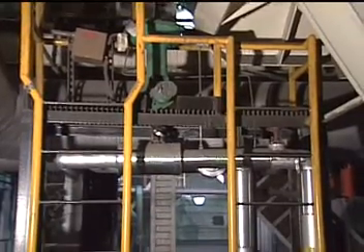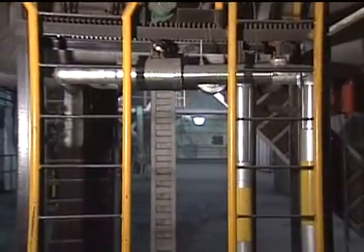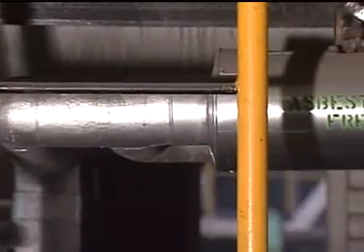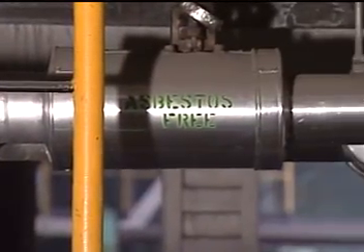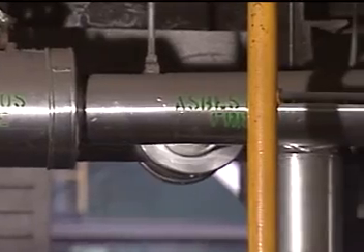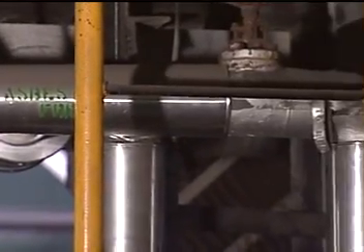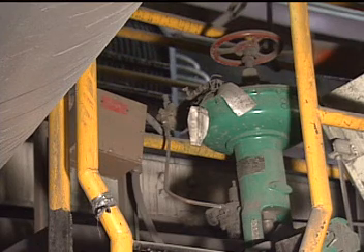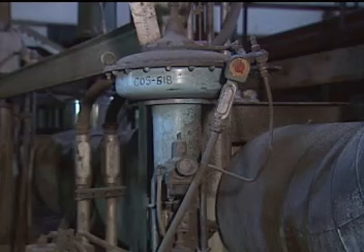The components of the temperature regulating branch of the control system are similar to those of the pressure regulating branch. However, the components in this branch regulate the flow of water to a de-superheater rather than the steam pressure that's supplied to the auxiliary steam system. For this reason, the valves and piping in the temperature regulating branch are usually smaller than the valves and piping in the pressure regulating branch.